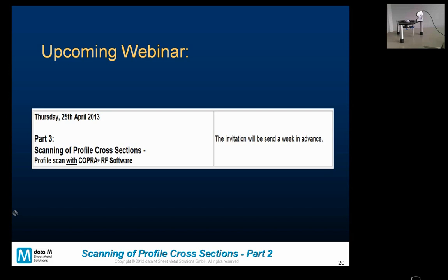Polished is sometimes a little bit difficult because you have high reflections, but we know there is a kind of spray available so that you can make the surface a little bit matte, and then it's again possible to measure the thing. Translucent?